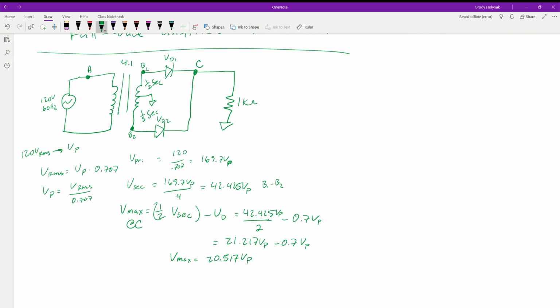So the reason for this is that when we're transforming, we have a coil coming from the top of the transformer to the center tap, but the other one's coming from the bottom of the transformer up to the center tap, because that's where our ground is and our current is going to flow. And so what happens is we're going to get 2 waveforms coming out of these.